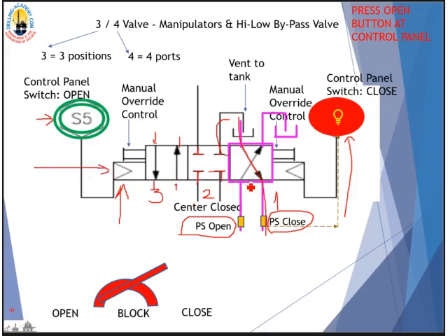It will pull the valve sleeve from where it is right now at the closed position to this open position here. All right, this pink square will move to here. All right, and this open line here will be pressurized because the input here will feed through it. Okay, it will send the pressure, and send the signal to light up the light bulb here.